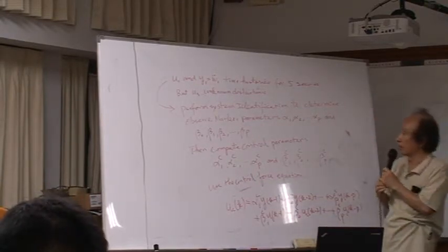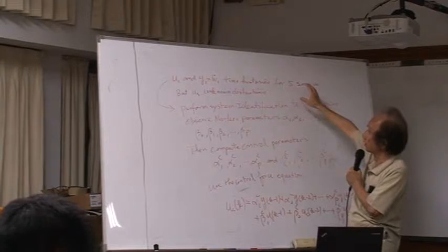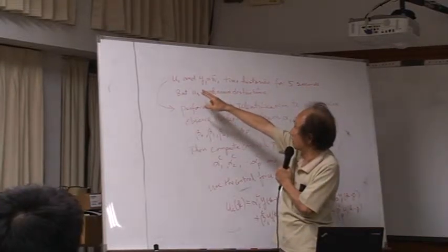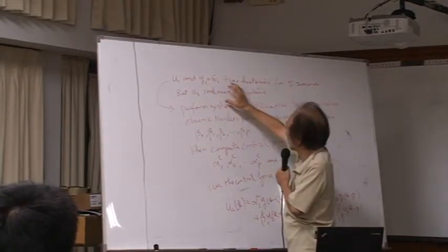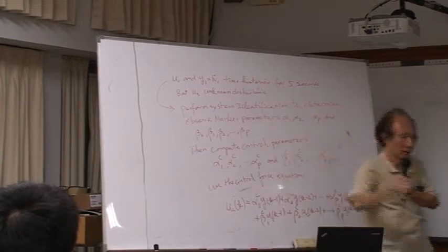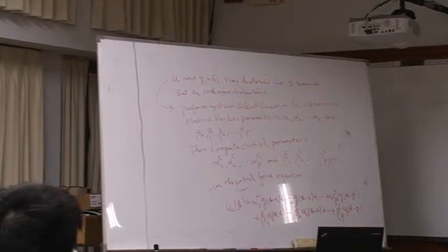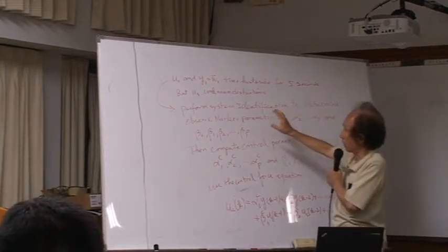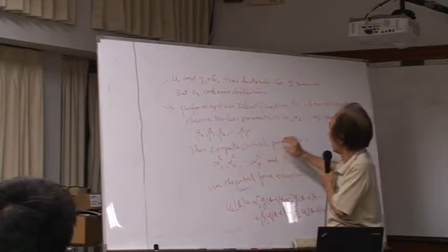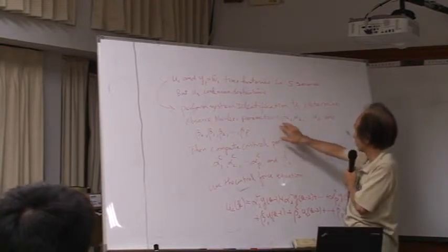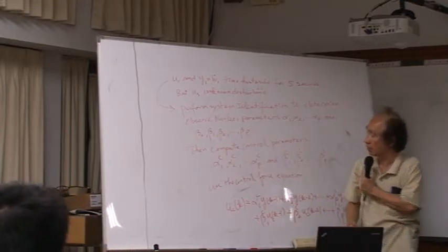That's a step. So in this chart, we have 5 seconds input, that's random input, and output Y1, but we don't know this. But this one also excites the system. So we have U1 and U3 to excite the system. But when we do system ID, we just use the input we know, the U1, and the output Y1 we know to compute alpha 1, alpha 2, alpha P to beta 0, beta 1, beta 2, beta P.